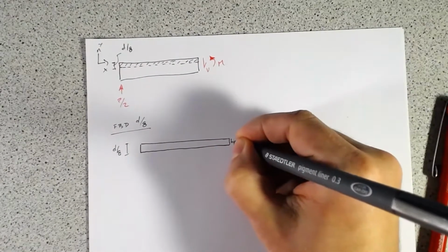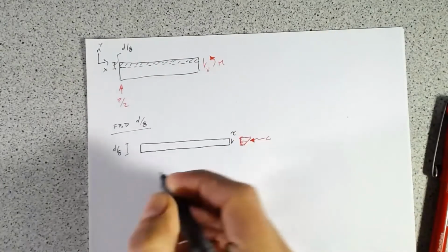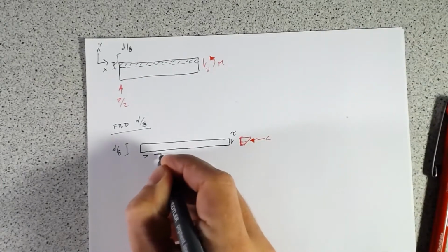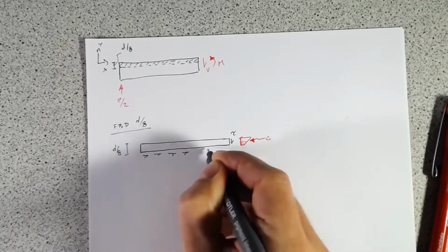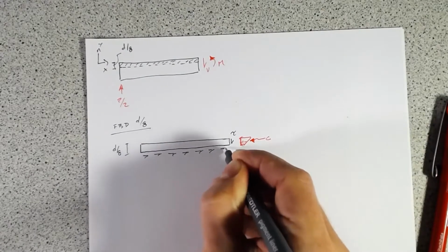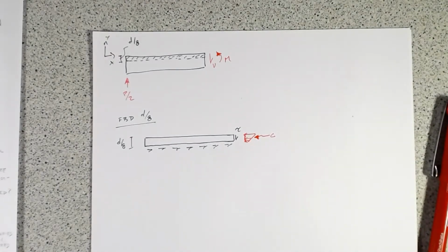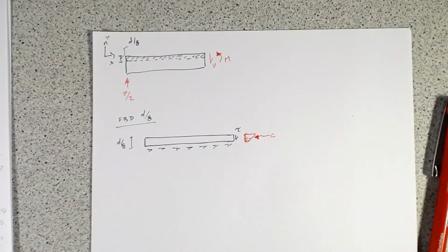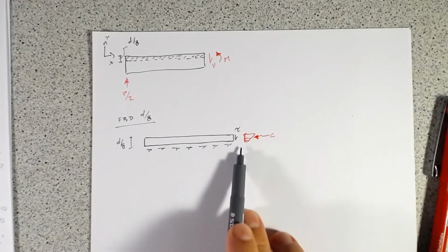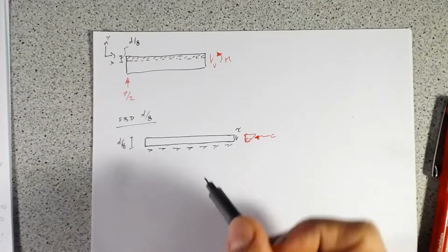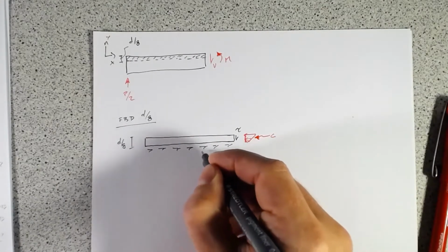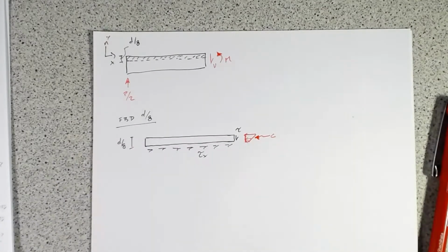Well, we know that we also have a shear stress, tau, and we're going to have a shear stress which is acting all along this cut edge. And this is what we saw with our derivation of general stress: if we have transverse shear, we have to have longitudinal shear. So we'll just call that tau x.